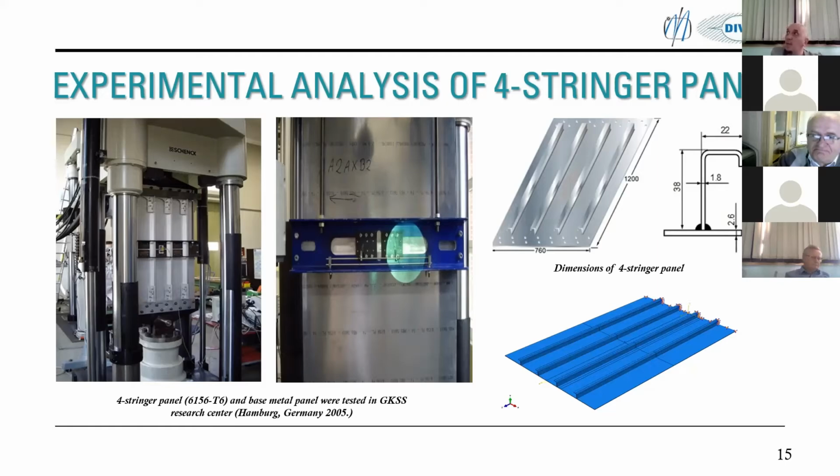In aircraft design, we call them stringers. So these are longitudinal elements, and they usually carry longitudinal force during the flight. So the goal here was to analyze the crack growth through the structure and to analyze the influence of stringers, the influence on reduction of the fatigue crack growth rate during the experiment.